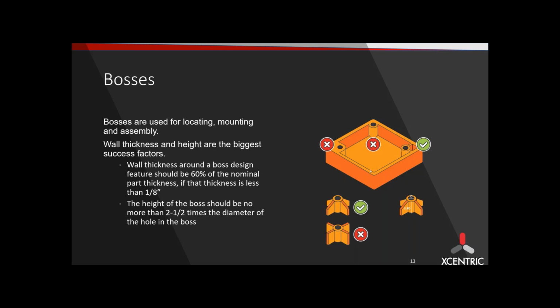And just to add on to bosses, sometimes you want to either overmold inserts, brass inserts, or heat stake them in later. When designing those bosses, you just want to make sure that you're following the recommendations by the insert supplier for the design, the OD or the ID, the requirements for those. Because if the boss is not designed thick enough or correctly, the inserts may not fit or may not hold to what they're supposed to. So something to just keep in mind.